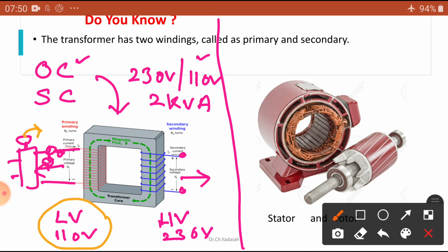This can be useful to understand clearly our 3-phase induction motor. Okay. Now, give the connections as per the circuit diagram. You have to remember that the HV side should be open, there is no load connected here, and on the LV side the voltmeter, ammeter and wattmeter are connected with the help of the single phase variac.